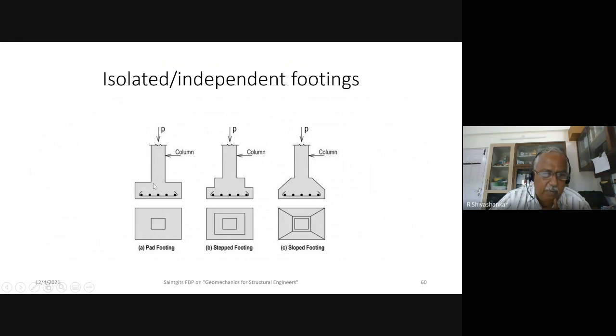That means you can have a top layer of reinforcement, and between these two layers you can have vertical bars. You can bind them to the top grid and bottom grid. With those shear reinforcements, the shear stresses are not taken only by concrete. Of course, there is some shear stress taken by the main reinforcement, but you can also have shear reinforcement.